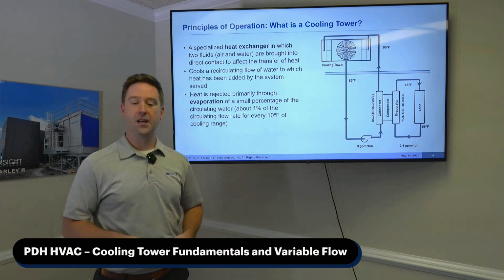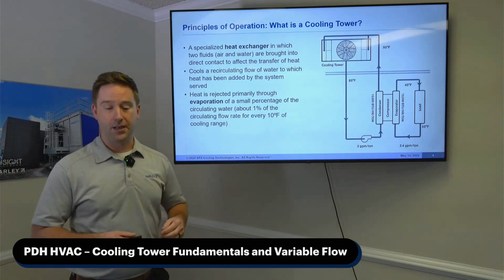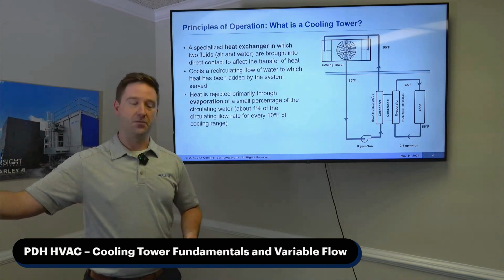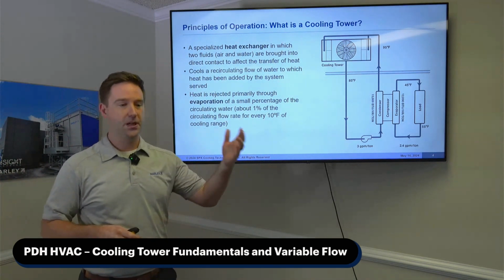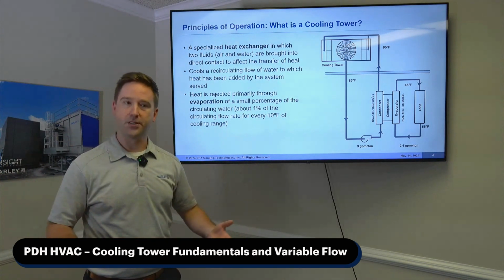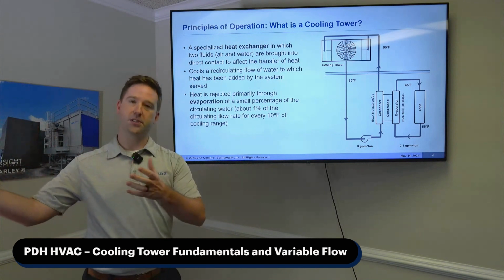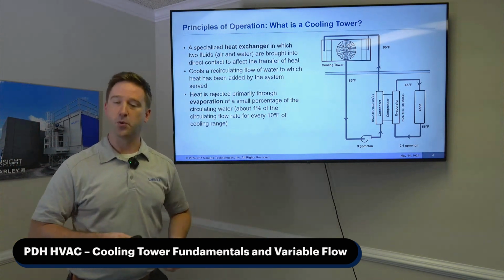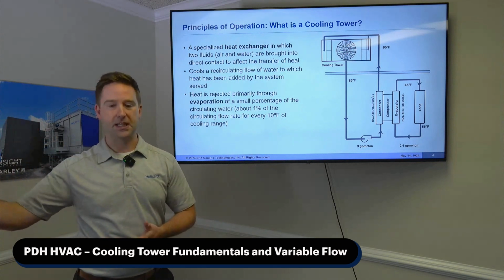So simply put, a cooling tower is just a heat exchanger. All you're trying to do is remove the heat from your chiller in an HVAC system. And so that's what it's doing. It's pulling your process fluid into the cooling tower, trying to evaporate some of that water, which is where you get a lot of that cooling. And I'll dive into that a little bit more.